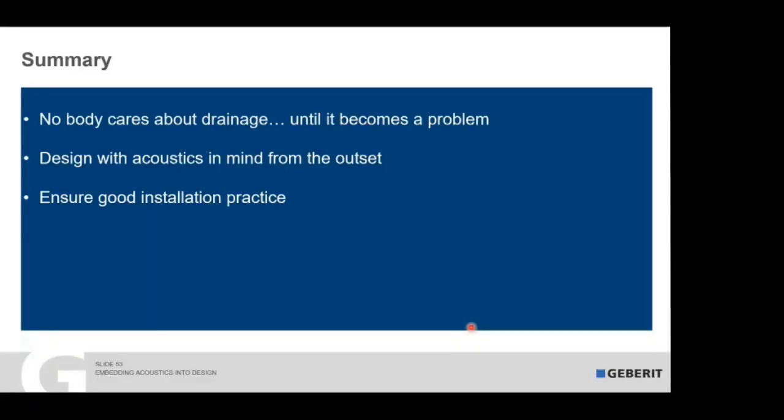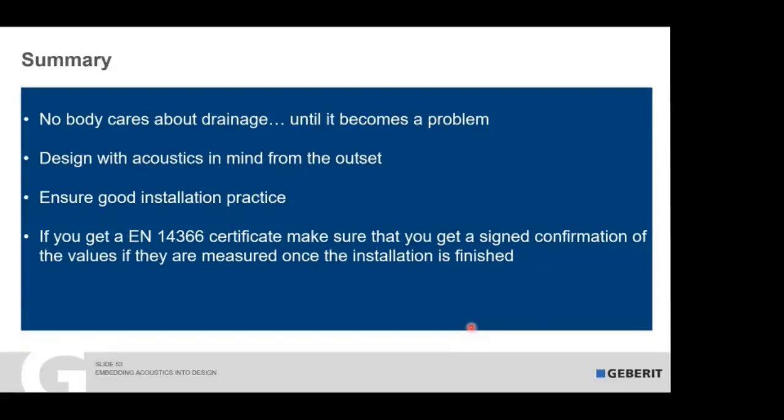So here, as I just said, ensure good installation practice. That's important. And then also from our side, if you get the EN 4366 certificate, make sure that you get a signed confirmation of the value if they are measured once the installation is finished. So if you get such a certificate, which is stating 15 or 10 dBA, just make sure that, once everything is installed, you make professional measurements in your room, that you will get these values.